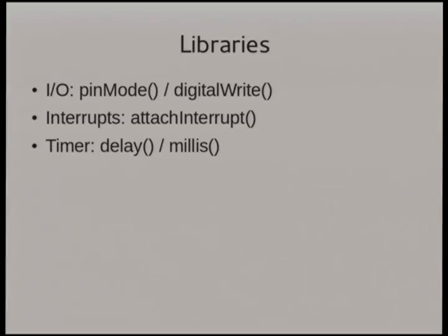For interrupts, something like attachInterrupt, say when pin 2 is rising, I want to schedule an interrupt to this function. With timers, it's not really the way that I was thinking about it when I was using Arduino, but really it is. There's a clock in the background that's counting along, and when you call the millis function, it just grabs the current value of that clock. And similarly with delay, it just sets up a thing that can wait for the clock to advance the right amount of time.